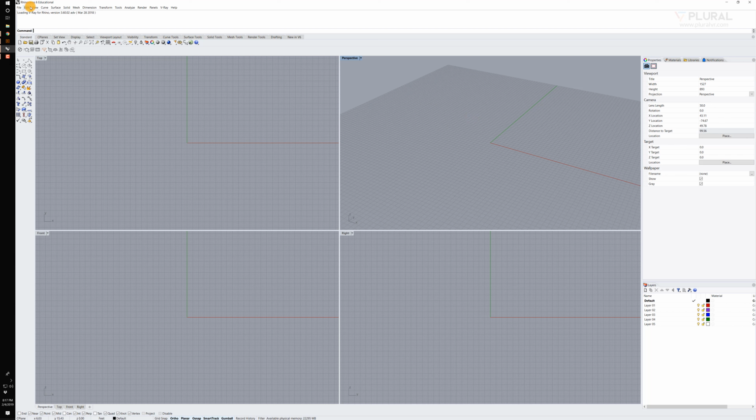First, you can see here I have lots of different toolbars, and within toolbars I have objects inside of objects inside of objects, right? I think that this is a pretty difficult way to go about generating work in Rhino. What you see here is the command line. The command line lets me enter commands and operate on them. So I can type box, and this lets me make a box in 3D.